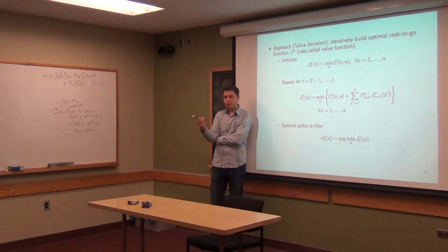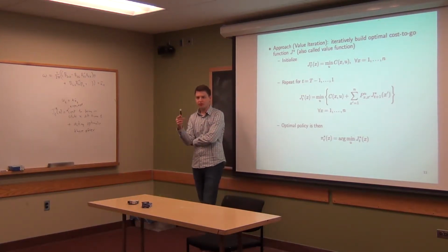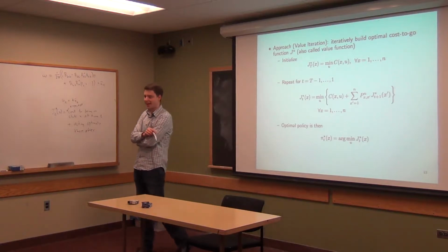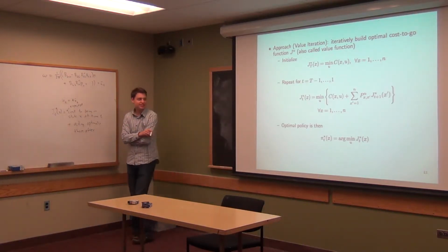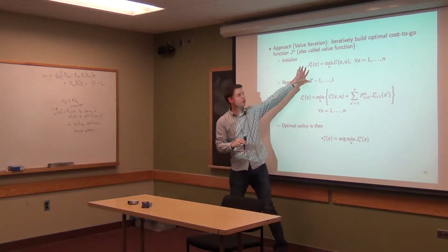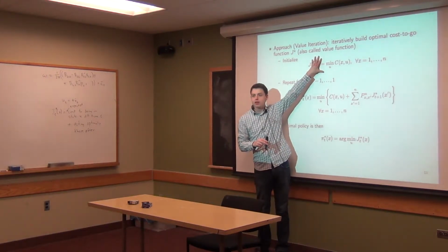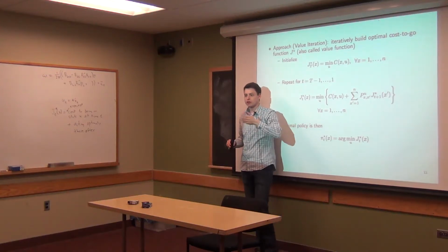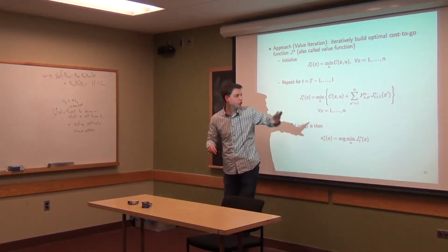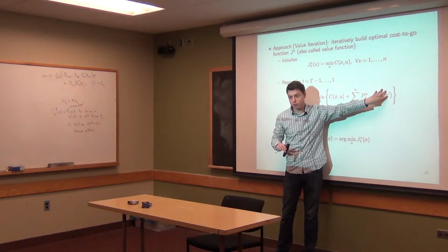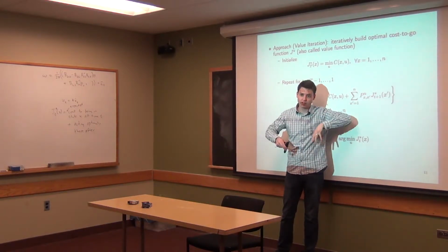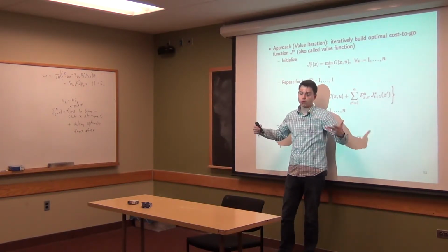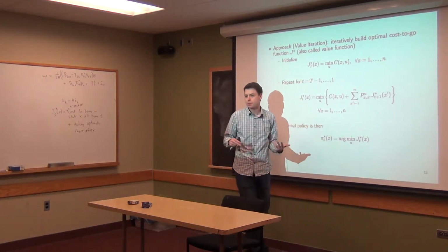And this is called dynamic programming, sort of an interesting, very catchy name, but basically all that it means is that we're using our past computations in computing our subsequent computations, right? So we're using this J star which was computed at the previous time to do our next computation. And that's all that dynamic programming really means in this context.